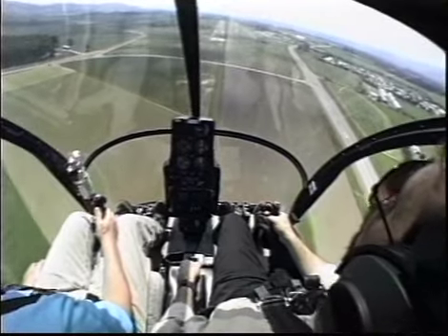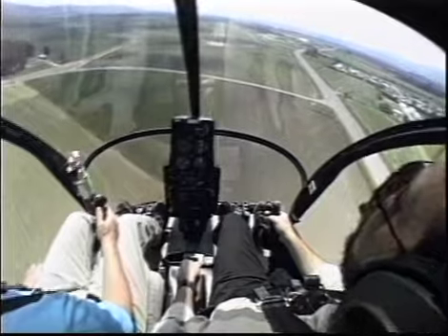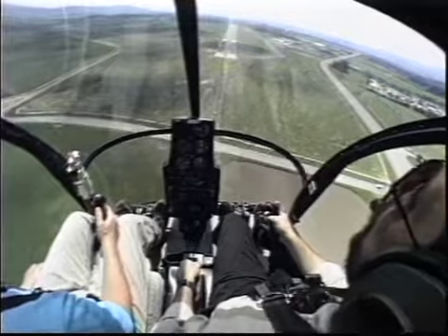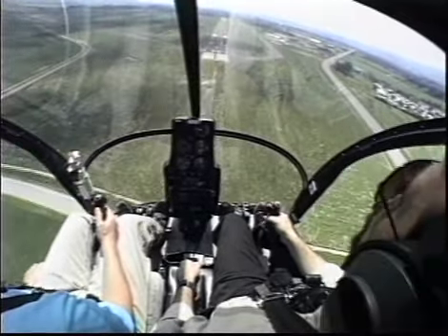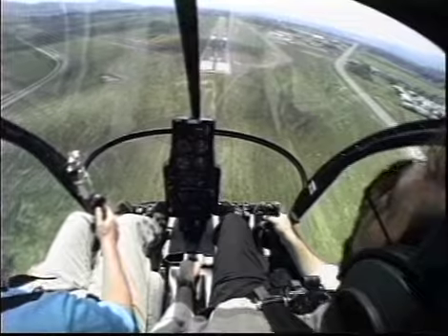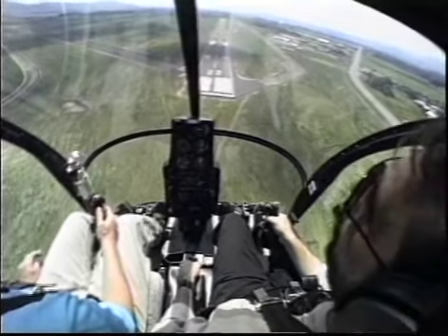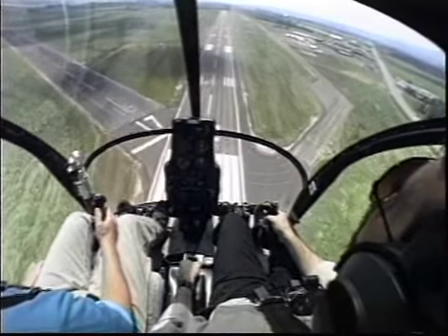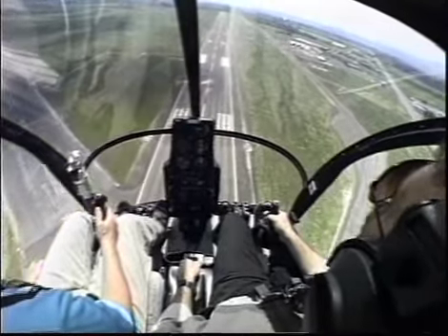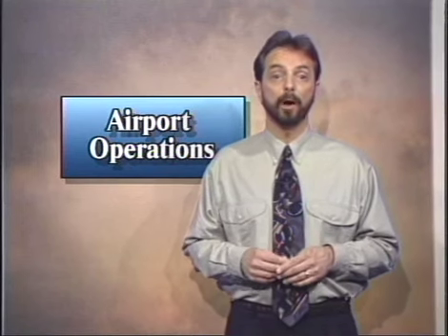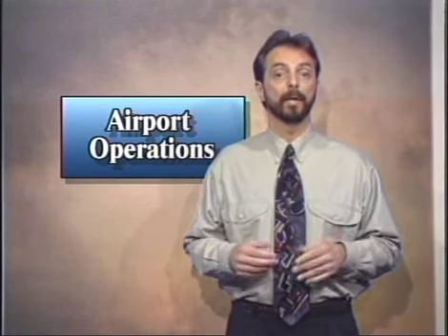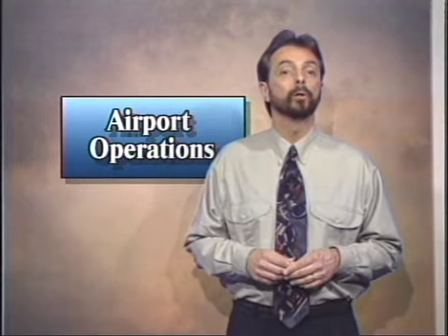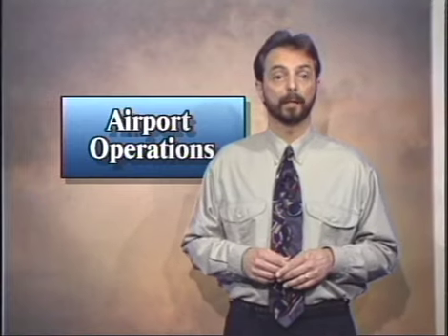Typically, helicopters fly the traffic pattern at half the altitude and distance from the runway that airplanes do. For example, 500 feet AGL and 1/4 mile. It's also not unusual for helicopters to fly the opposite of the standard pattern. For example, if a particular runway is left traffic, a helicopter might fly a right pattern. These are the usual ways in which helicopters avoid the flow of fixed-wing traffic. Keep in mind, too, that helicopters will often fly direct to a specific point on the airport and avoid the traffic pattern altogether. There will be times when you'll be operating to and from a public-use helicopter landing area.